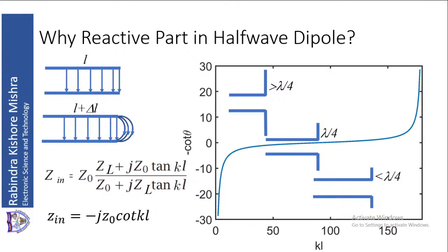The vertical lines, upward and downward, are flared up regions of the transmission line. One is flared up in the vertically upward direction, the other is flared up in the vertically downward direction. And that total flaring length, upward and downward, if we combine them together, then that is lambda by 2. So when we say antenna length is lambda by 2, or it is a half wavelength antenna, that is the total length.